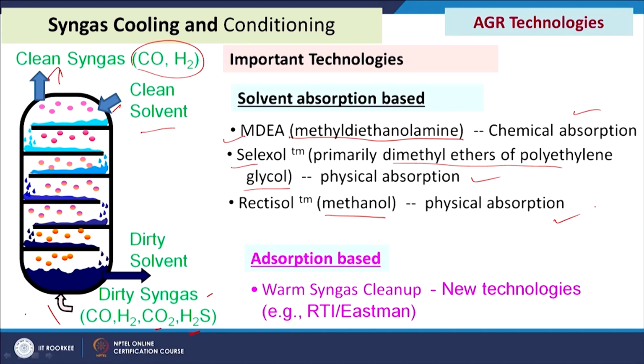Now, in recent years some adsorption based technologies have also been developed, that is warm syngas cleanup, which RTI and Eastman company have developed. They use some metal oxides which capture H2S. Now, we will see the comparison among these processes.